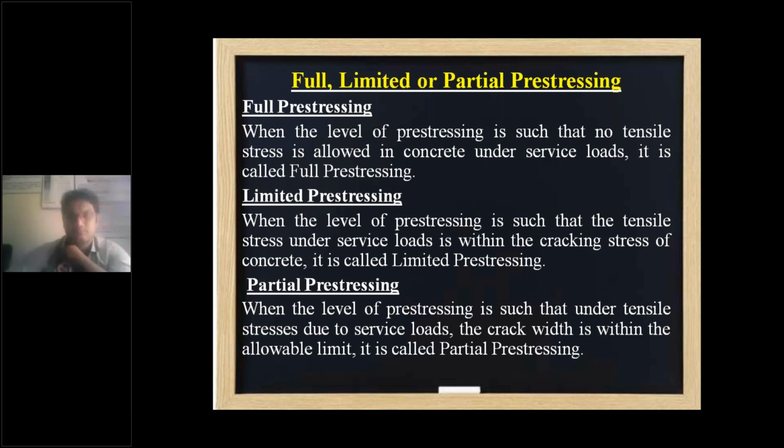Some elements may require only partial pre-stressing, some only limited, and some full pre-stressing. If you do partial pre-stressing now, in future if you want to increase the strength of that particular member, you can do further pre-stressing there. So partial pre-stressing is done for a few elements, to be stressed later to improve their strength. Like that, stressing can be done in three different modes: full, limited, and partial pre-stressing.